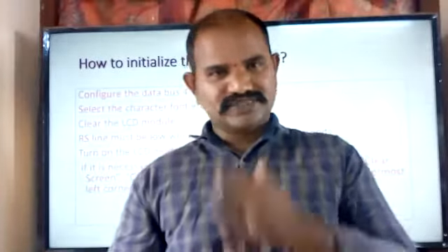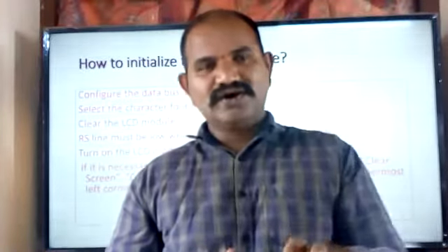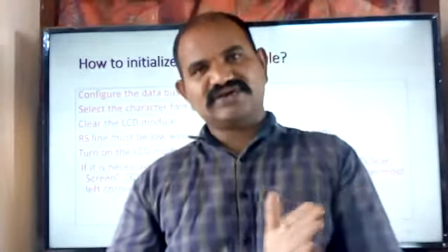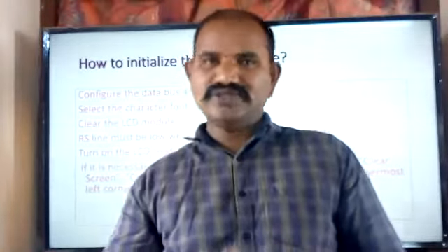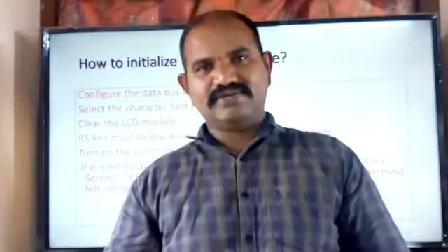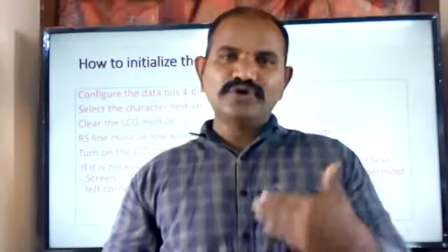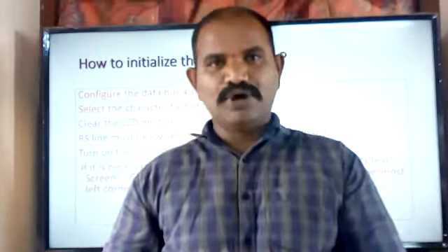Now, depending on your requirement, you can choose appropriate command words, and you can send those command words from the microcontroller to the LCD display in sequential order. Another case is, as I said, whatever information you would like to print on the screen of the LCD module, that information should be sent in the ASCII format.